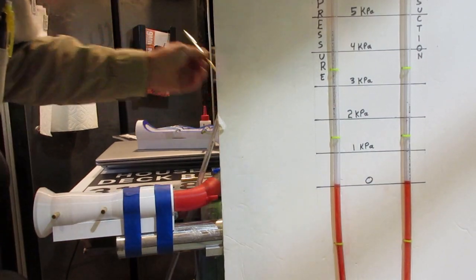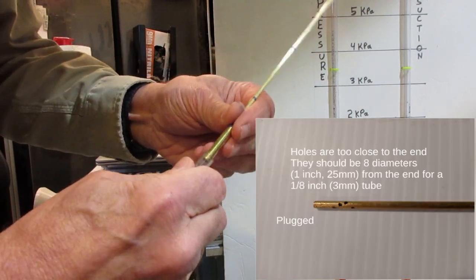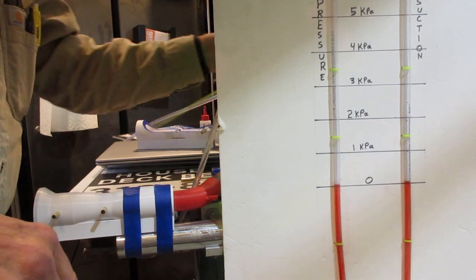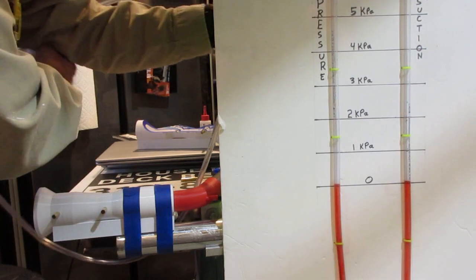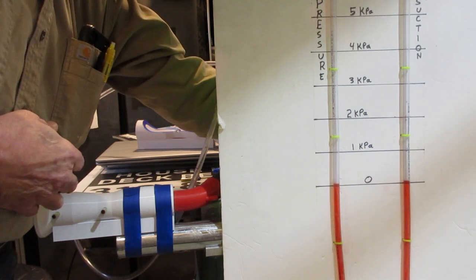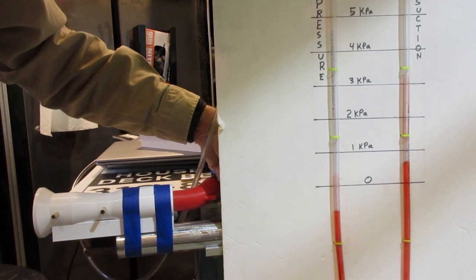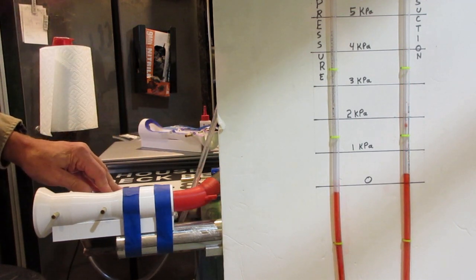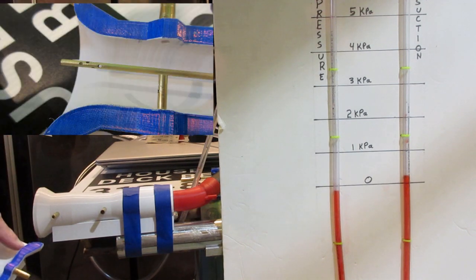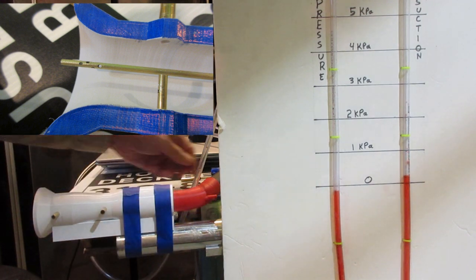Now we can take our static probe, the continuous probe. In spite of the fact I put the holes in the wrong spot, it still gives us pretty good results. So I can slide it into my adapter, slide it all the way forward, almost to the entrance of the Venturi. I'll point where it is right there on that cutaway. And we're seeing a little bit of suction as you start coming into the Venturi.